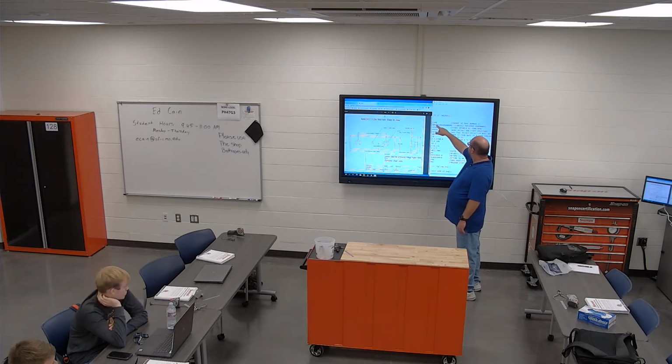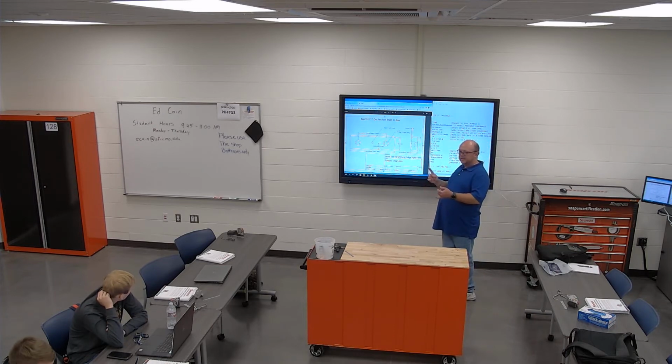And M6 is your tool change. So that's going to tell us to go to tool 1. This year we're keeping all the probes in the very last one. So the probe will either be 10, 20, or in the new machines it's 31.